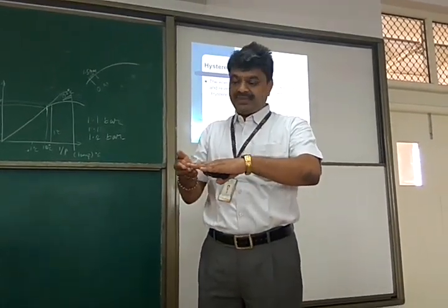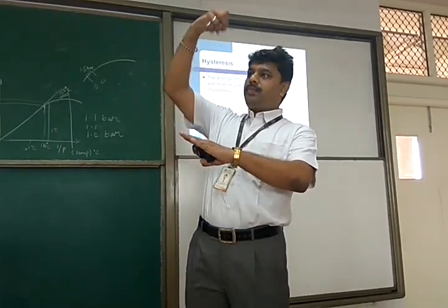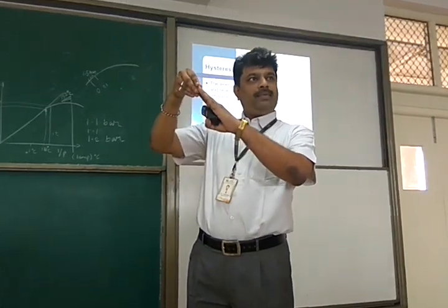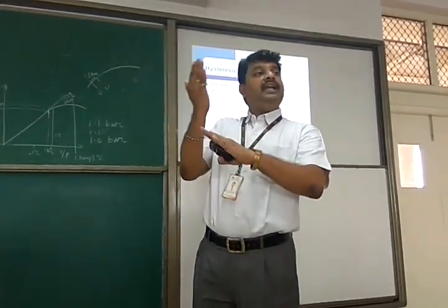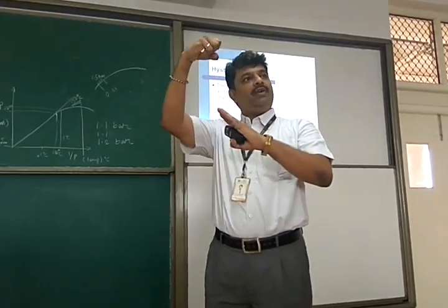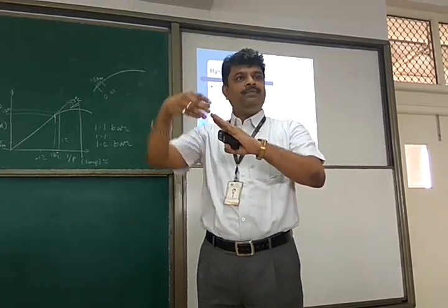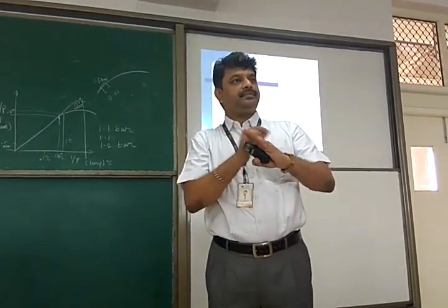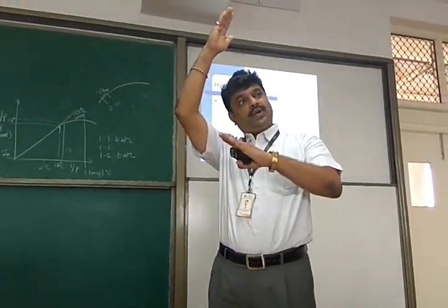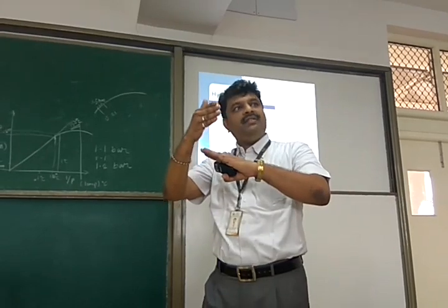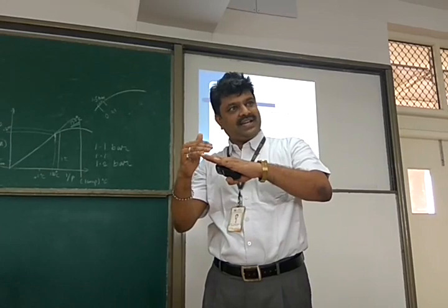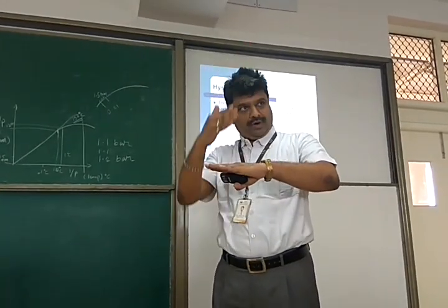That is the reverse path. And then minus. I put a spring balance and pull 100 gram pull, 200 gram pull, 300 gram pull, so that I am pulling the cantilever beam upward. Take the deflection, how much mm it is deflecting for 100 gram of pull, 200 gram of pull and things like that. And that also I take the reading. Okay, that's a complete reverse path going up to 1 kg, minus 1 kg on the outside. Again coming from there, minus 90, minus 80, minus 50, minus 40, minus 10, 0. Then it has reached. That is the forward path.